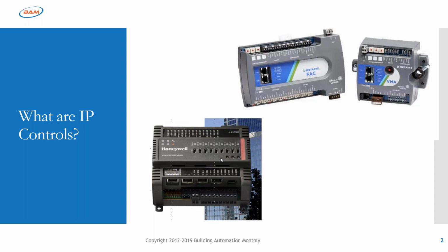And what data is it going to drop? Well, the data that has no quality of service tag, like building automation data. So you'll see this in data centers where they're doing massive data updates at night and the BAS starts to go offline. And so that is one of my biggest issues with putting cameras and other things on a BAS